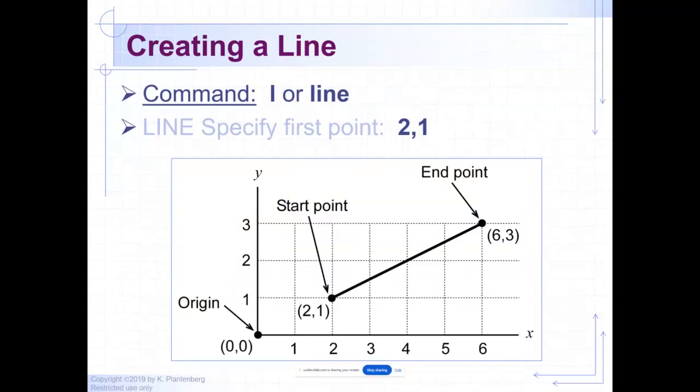Okay, so we're going to go through this here in a few minutes, but like if you use the line command, you just type in L, enter. Anytime you type anything in AutoCAD, you have to hit enter. Now, what's the other button that you can hit besides the two enter keys? You can hit space bar. And you can also right click. And if you have it set up like I like to have it set up, when I right click, it's enter in certain cases.